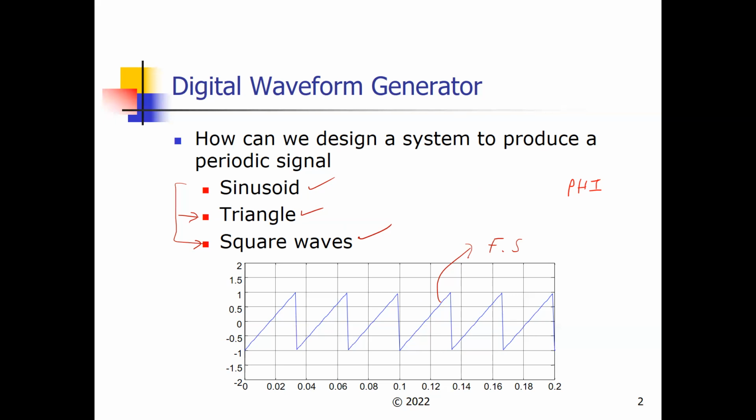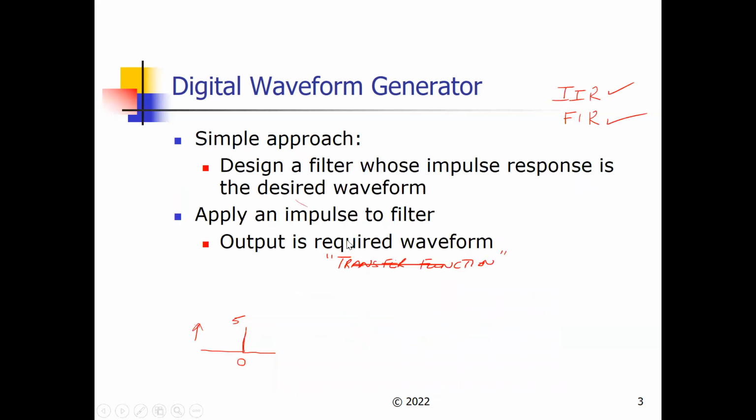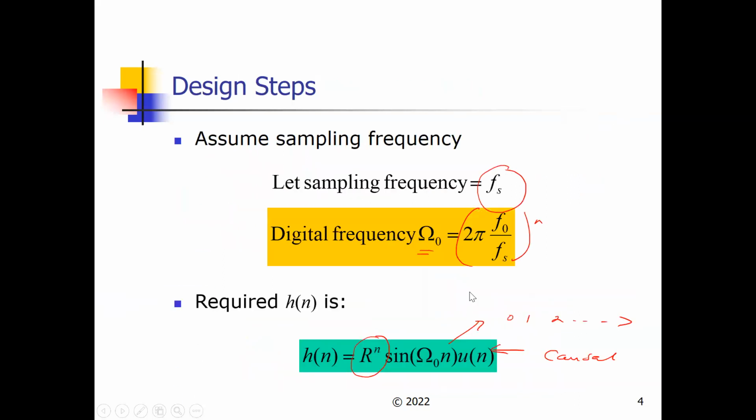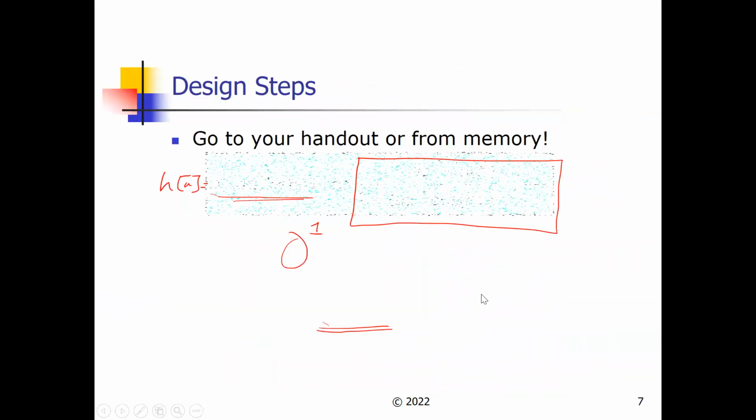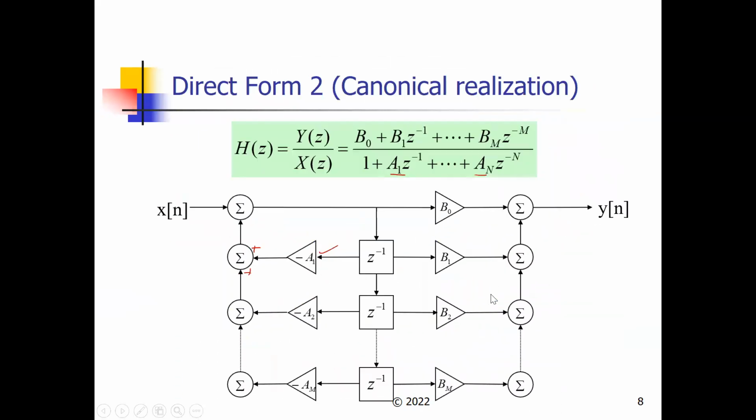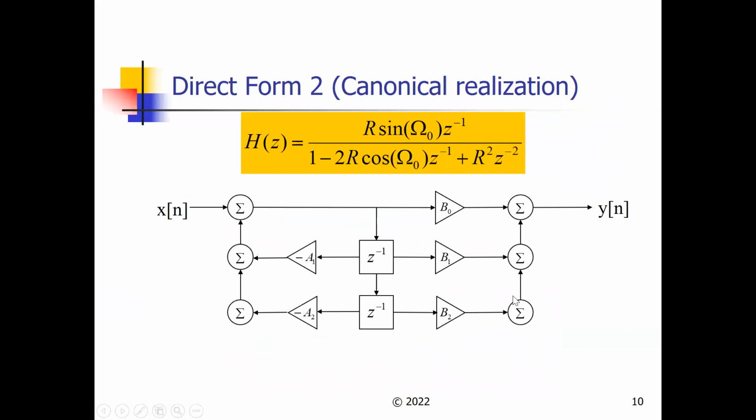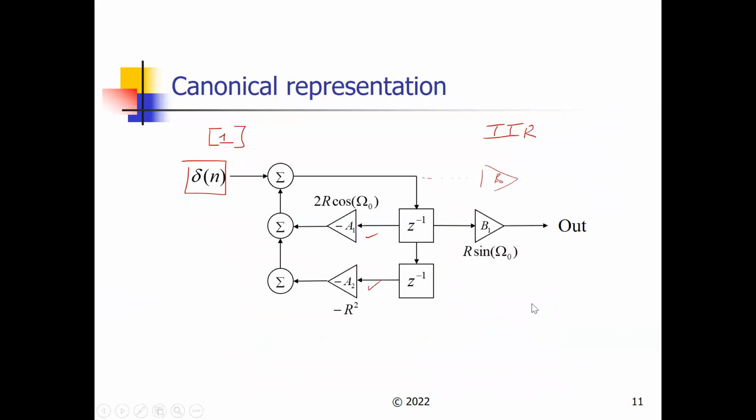Once you generate one, the programming aspect for generating one sinusoid is this. This is a single sinusoid right here, of frequency omega 0. So if I wanted to generate 2 omega 0, 3 omega 0, up to 50 omega 0, the process is still the same, right? Just put them together, and as the impulse comes in, it generates all of them together, adds them up, and you get your particular waveform being created. Triangle, ramp, square wave. You can do it as many as you like. So it's the same process.